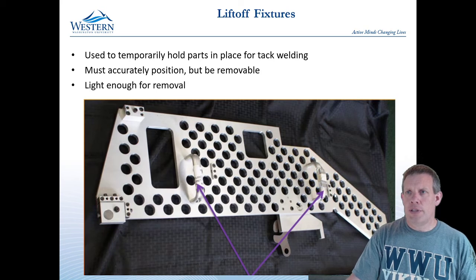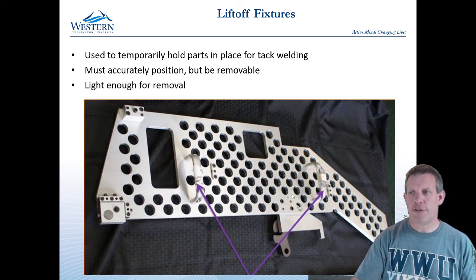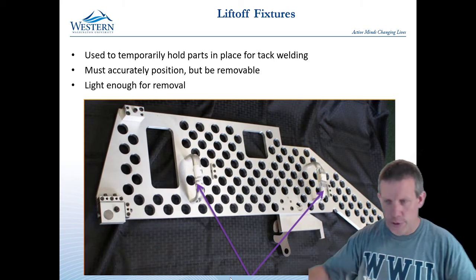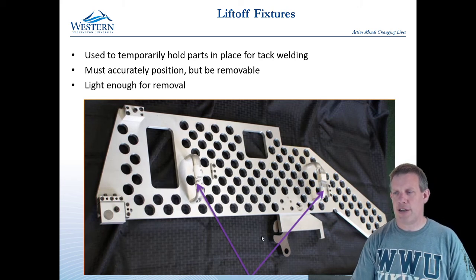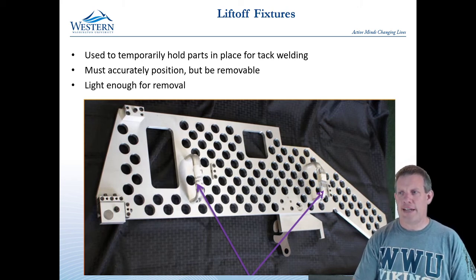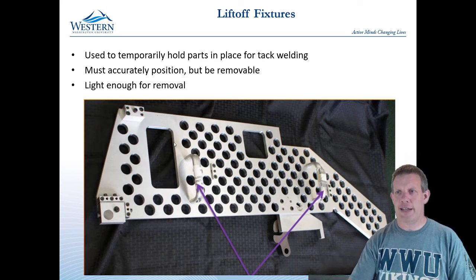time. Some ideas for welding. One idea is to use these lift-off fixtures. So you can use this. You can see how this entire thing would be put down. It has some guides to hold it in place and a locking arm right here. It also has handles to make it easy to put in, and then it has these big areas where the welding is going to happen.